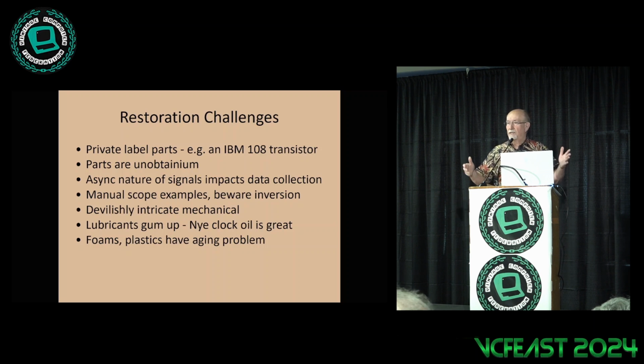The foam that they use for soundproofing turns to dust, or it turns to tar, or it turns to both. So you have patches of goop and patches of dust. Got to scrape all of that junk out of there. The plasticizers and the plastic parts have all evaporated by now. So they're now brittle. So something that was just perfectly fine before is going to snap.